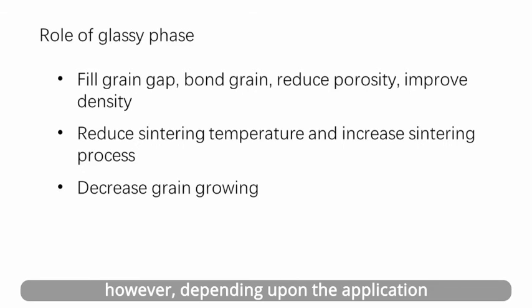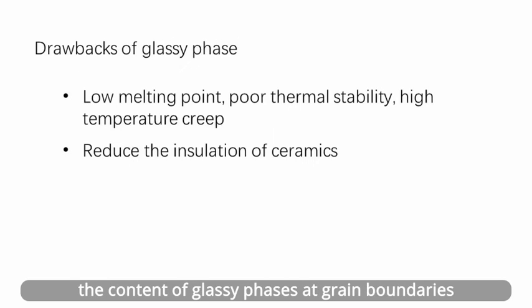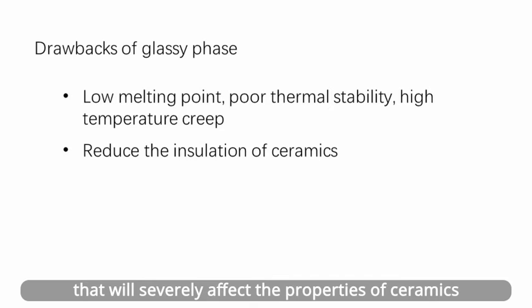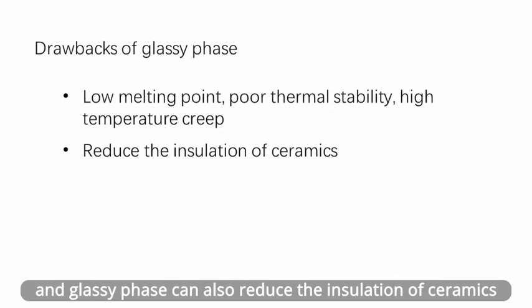However, depending on the application, the content of glassy phase at the grain boundary also should be considered. Usually, the glass phase has a low melting point. It has poor thermal stability that will severely affect the properties of ceramics when used at high temperature. And the glassy phase can also reduce the insulation of ceramics.